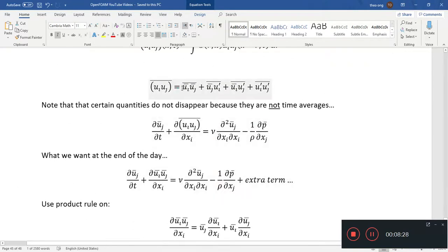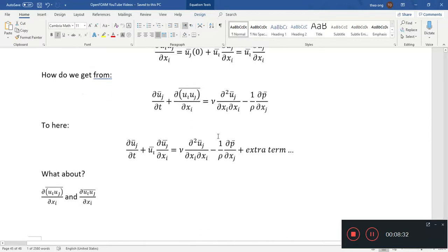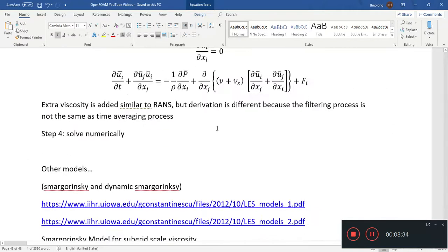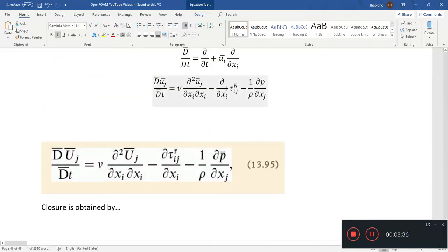They will contain all of these funny little terms, and they will account for that difference. These are the residual terms, the Reynolds stress terms, which are caused by the subgrid scale turbulence.